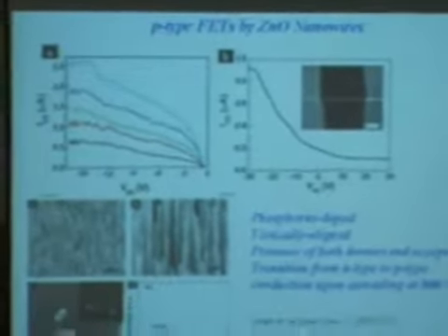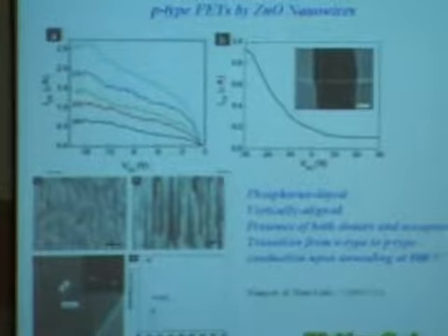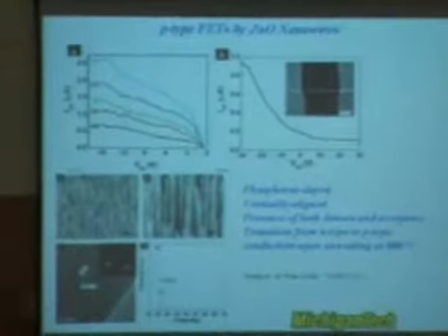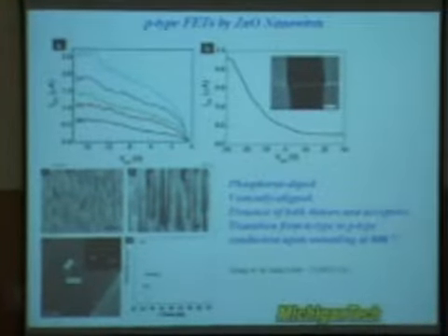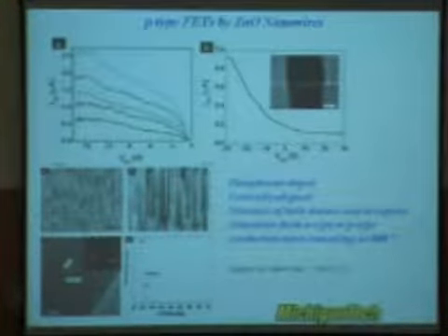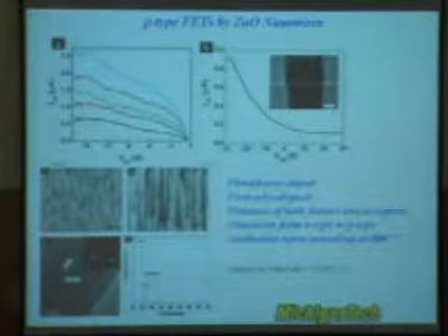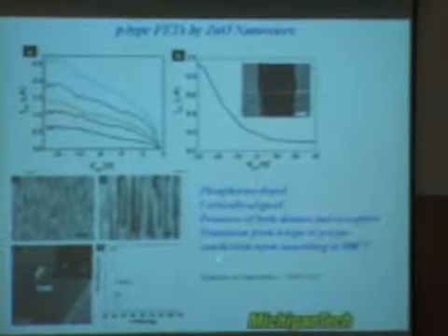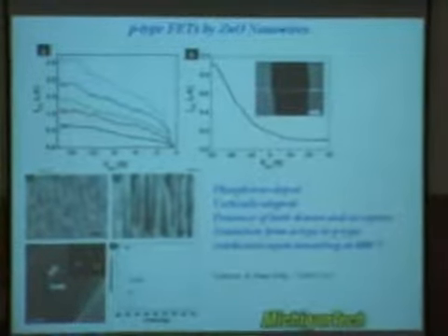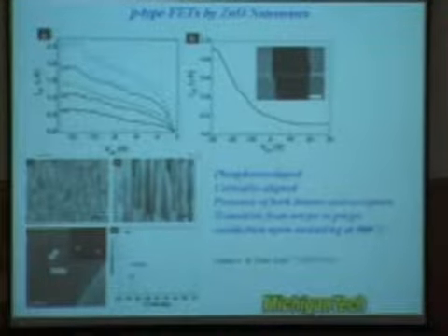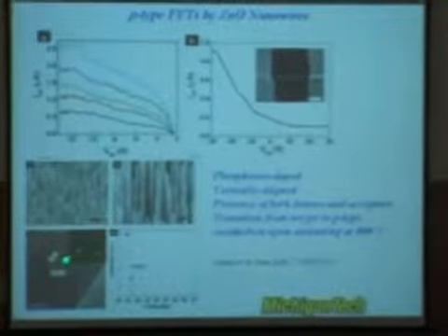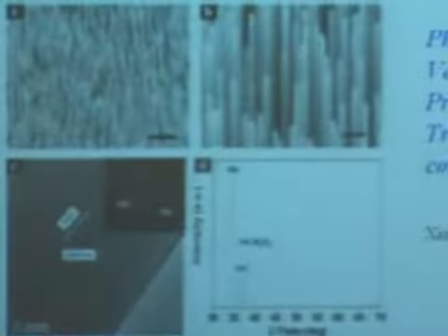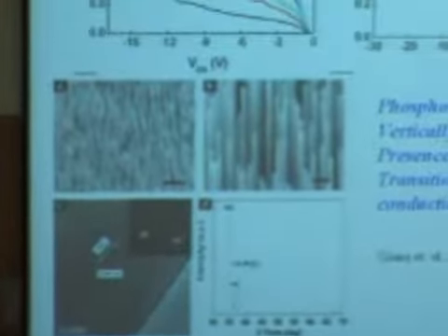And you can actually see that some of the devices demonstrated on zinc oxide always behave as N-type, because oxygen tends to have vacancies inside the zinc oxide. And it's very challenging to make P-type materials, and it was just published this year. So I'm giving you the latest information, all right? So it can be done, P-type and single crystal materials, and it shows the gate effect of the P-type materials. However, this type of P-type zinc oxide is still not very stable at this moment.